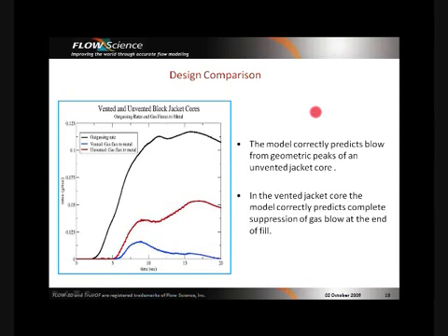The computed result is in good agreement with the experimental observations, especially later in the fill when the gas flow is almost completely suppressed. The gradual increase of the gas flow from the unvented core is also in agreement with the foundry observations, and this is the curve for the unvented core. The two peaks that you see here, peak 1 here and peak 2 here, roughly correspond to the two sets of bubbles seen in the experiments.